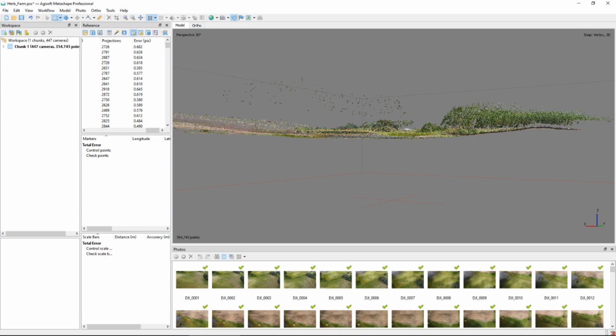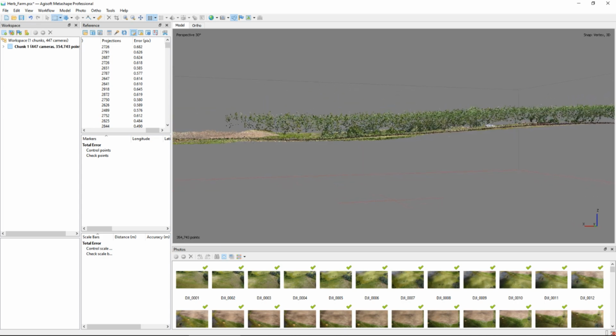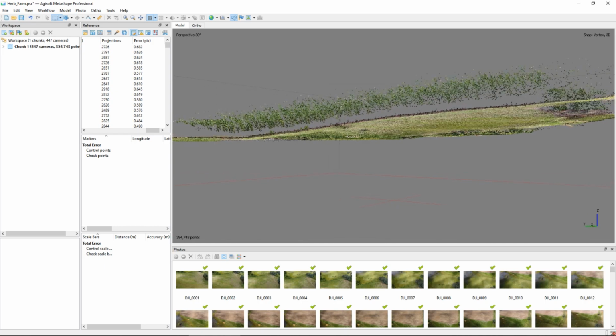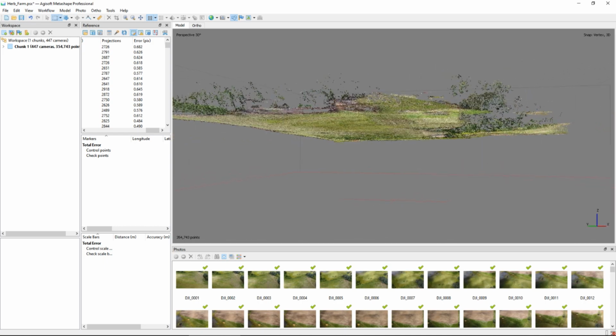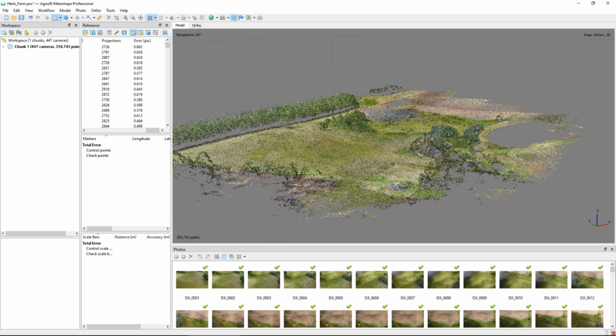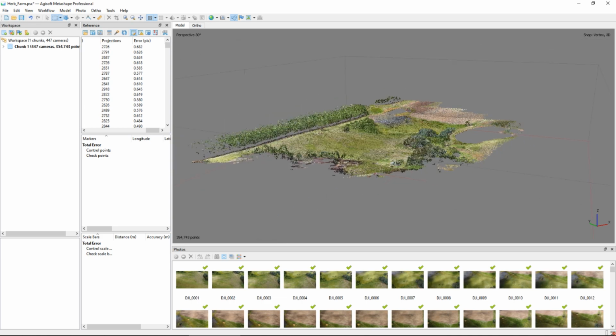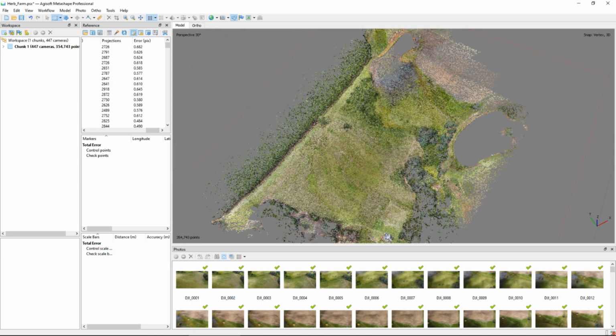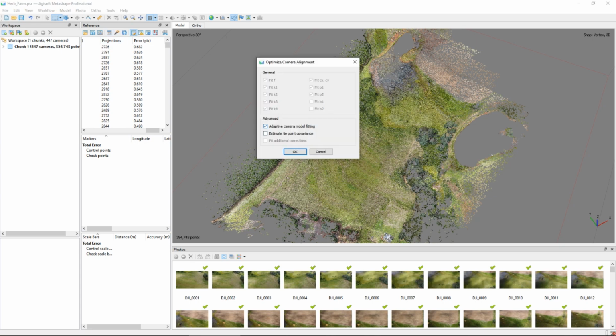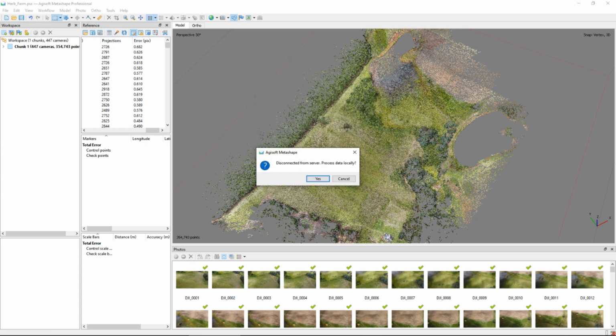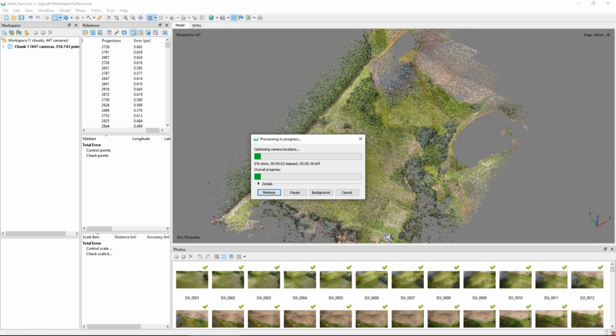If any points remain after this process, you might want to pan through the model, select them manually, and delete them, thus ensuring your tie points are all clean so that when we move on to the following steps, you're starting from the best basis point. Do a final optimization and save your project. Once that is done, we can move on to building the dense cloud.